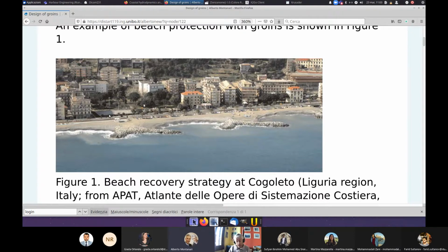And therefore you have a movement of the shoreline forward. And what you can see here, it's clear that this beach was moved forward by the creation of these groins, because if you look at their position and the pocket of sand in the U shape,